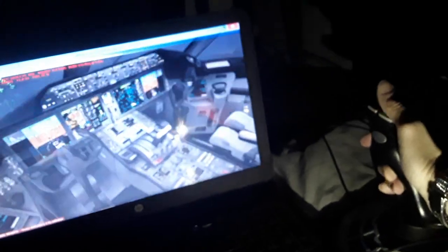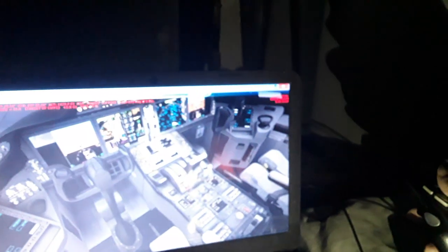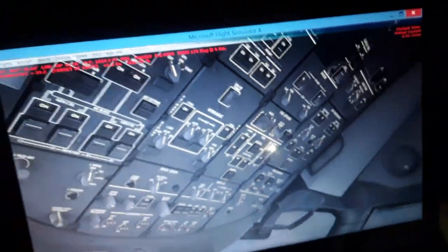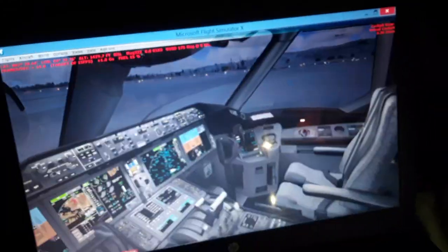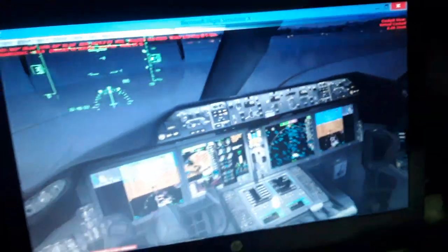So you see the flight controls. If I move the yokes here, you see everything is moving. We need hydraulic power from the engines to move the wings around. So the tail, the rudder, the speed brakes, flaps, landing gear extend and retract, parking brakes, auto brakes, thrust reverser for the engines. Everything needs hydraulic fluid pressurization. Over here you see the hydraulic fluid pumps actually, engine driven and electric driven. So this is all the things we need to know. So we need also pressurization to start the engine. We're going to start the APU in a couple of minutes.